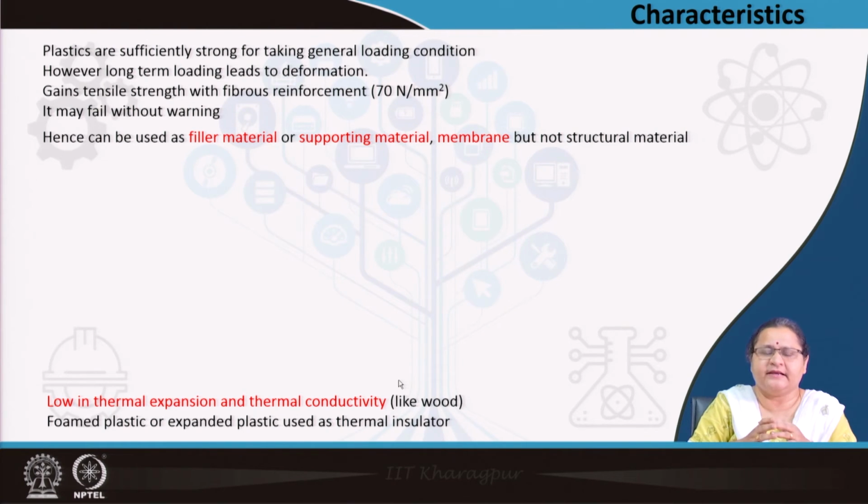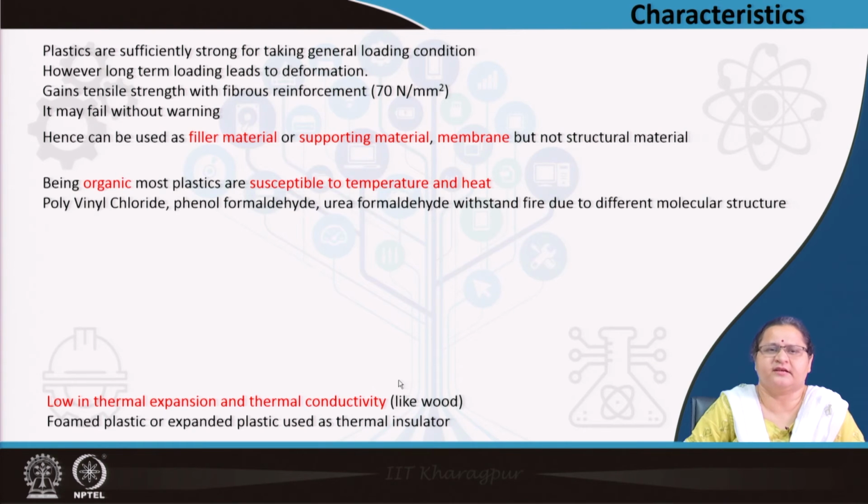They can even fail without any warning. That is why none of these plastic materials are recommended as a structural material. They are very good as a filler material, supporting material. Taking general loads, a seat, a chair, a simple table, it is okay. But beyond that, general plastics cannot play the role of a structural material.